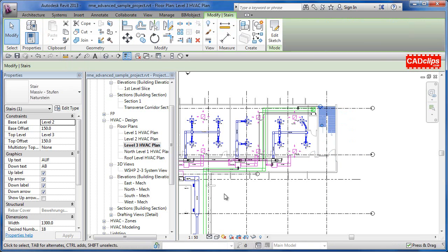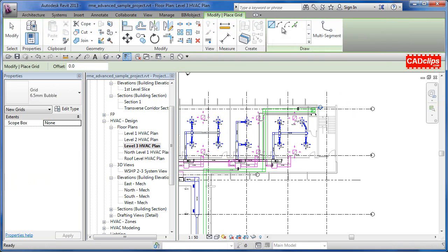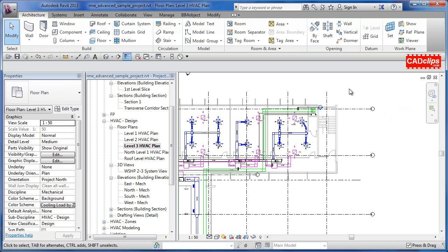The grid lines basically are drawn in a plan view or an elevation or a section, and they basically go vertically up, and you can create grid lines that are at an angle or also arced. So they can be straight and they can be different types of arcs, and you just start to pick and place them, and we'll talk about the fundamentals of putting grid lines in a little bit later. I'm going to hit escape once and escape again. So we have grid lines available here, and level lines once you get into a section or an elevational view.